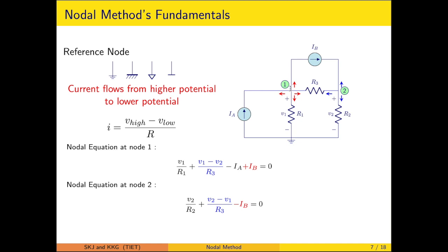So you have simply given the two nodes V1 and V2 marked there. Now let's write the equation for this. Correspondingly we have to mark the outward current as positive. These red arrows are temporary arrows, not the permanent ones. At this junction there is an outward current, outward current, outward current and outward current. So how will we write the outward current equation? V1 upon R1.